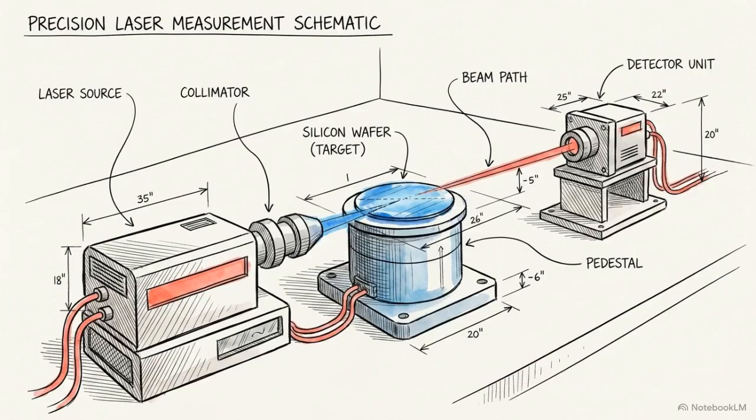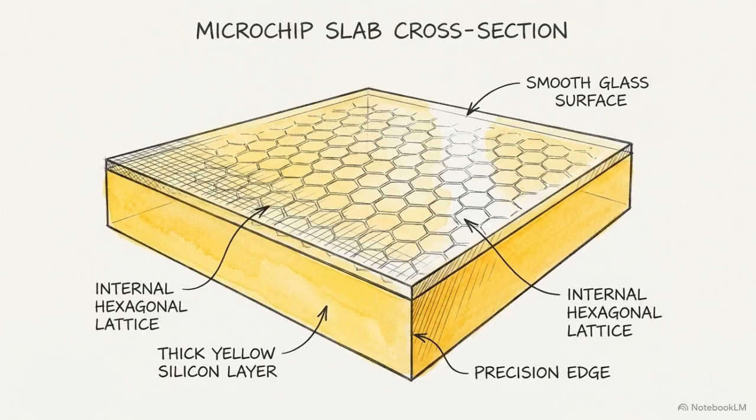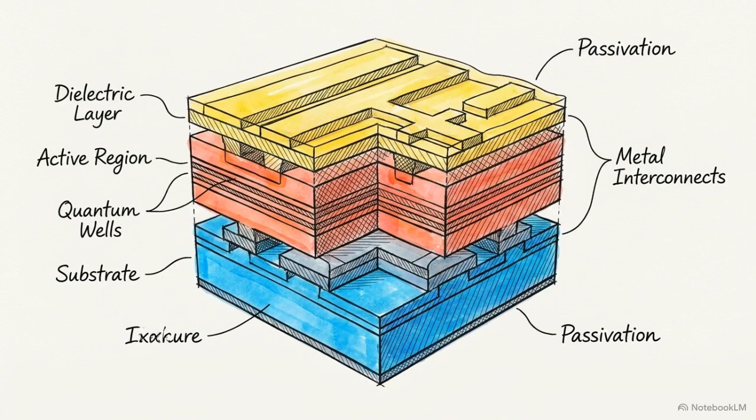To measure exactly how these forces interact, we can analyze the performance of devices across four highly specific silicon nitride thickness variables: 0, 20, 50, and 120 nanometers. Measuring the top layer in isolation presents an incomplete picture. The electrical response of the entire system depends heavily on the architecture of the underlying epilayers. We can observe this by testing two distinct frameworks.